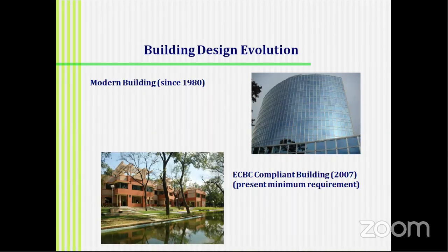And in fact, Griha or most of the sustainable schemes also dovetail the requirements of ECBC into their energy performance criteria. So the ECBC compliant design insisted upon insulating the walls, the roofs, and trying to have better kinds of glass, low emissivity glass, and it insisted upon shading devices, daylighting for buildings. So through these, there was a lot of efficiency that was incorporated into buildings.